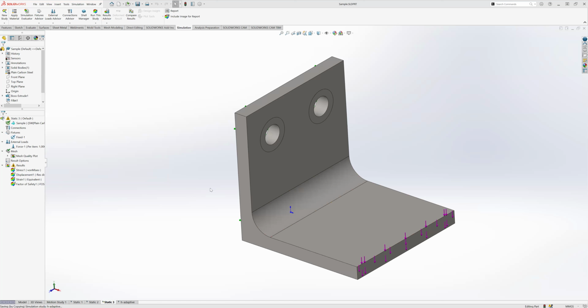I think the last time we talked about meshing and how, obviously, in areas of curvature you want to make sure your mesh is actually mapping the area properly. So if you have areas like that, you may want to go in and make the mesh finer. But then you start running into a problem. If you make the mesh finer in the entire part, when you really only need a fine mesh in one area, you're going to increase your simulation time for pretty much the entire model when you really don't need to. If you have a decently fine mesh here, and you have enough elements across, you really don't need a super fine mesh everywhere if there's only one area you're concerned about. So that's what I'm going to go into today.